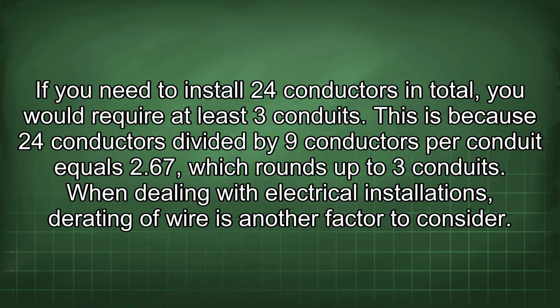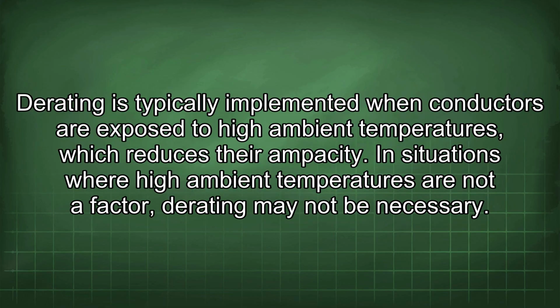When dealing with electrical installations, derating of wire is another factor to consider. Derating is typically implemented when conductors are exposed to high ambient temperatures, which reduces their ampacity. In situations where high ambient temperatures are not a factor, derating may not be necessary.